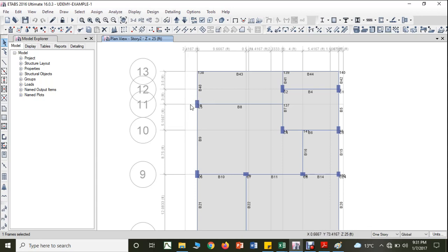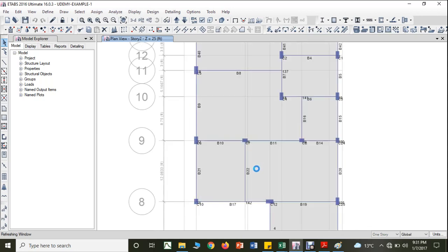It will bend along the longer direction, that is this direction. Therefore, in such case I am supposed to take D as this longer direction value. Now here if you see, they are connected by main beams. Here also main beam, here also main beam. So I can see this column will try to bend like this only, that is along this direction.